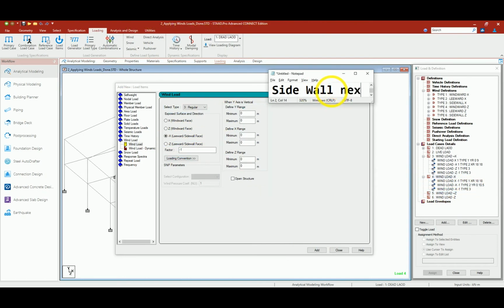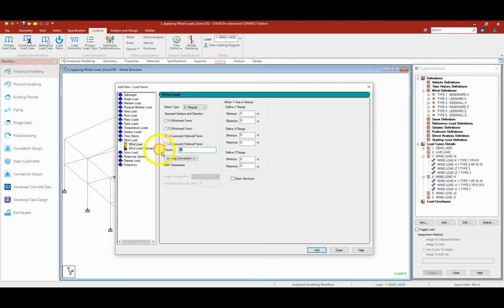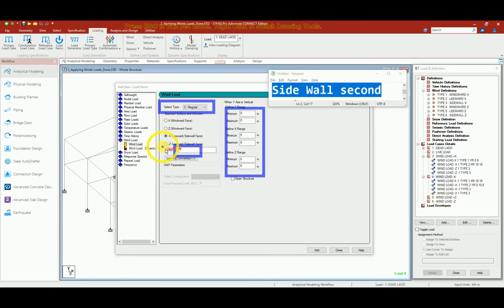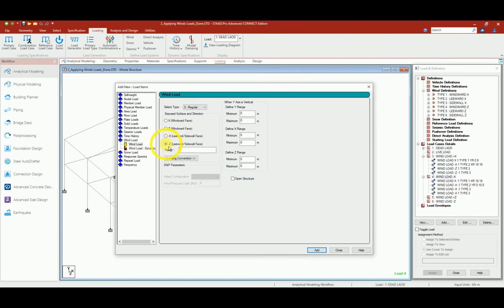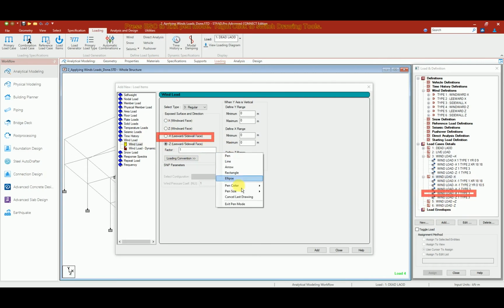This I have taken incorrectly again. I will modify it. Wind load in -x. This should have been the Z for side walls. That is the last option I should have taken. As can be seen from the data window, for the load case number 3 I have taken correctly. So this should not give XXX in all the cases. So I will again add the correct one and delete one case.